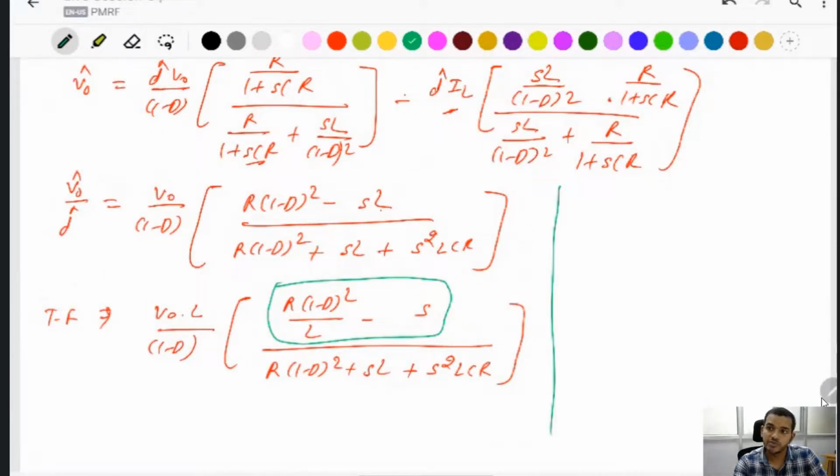It reduces the phase margin. If you reduce the phase margin, then the zeta value should decrease, and you find the overshoot also increases and the phase margin decreases. Because the phase margin is equal to 180 plus the total phase angle, but when there is a negative term here, this one is more subtracted from the 180 degrees. This means the phase margin reduces, and so the peak overshoot also increases.